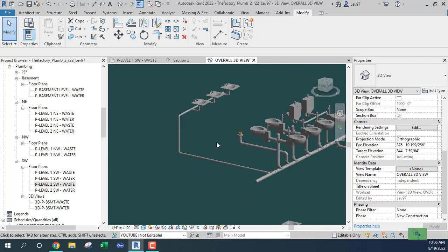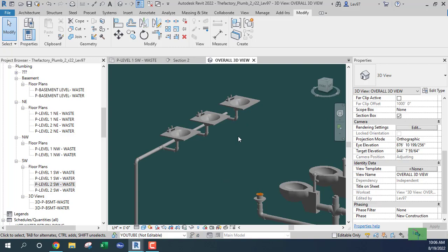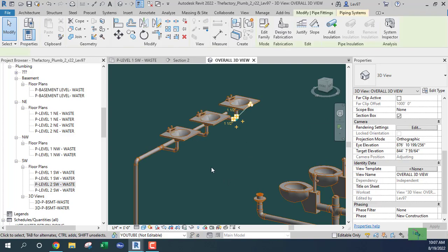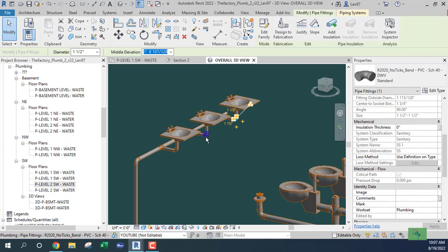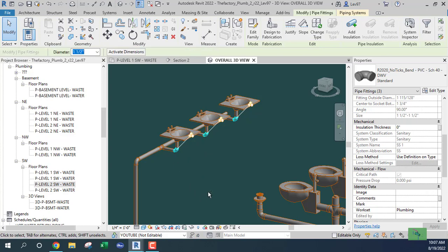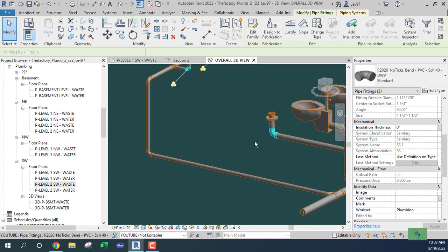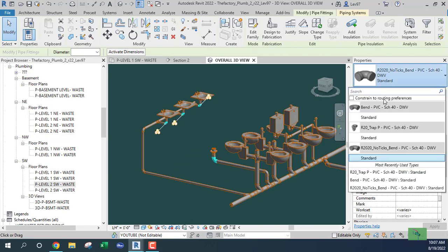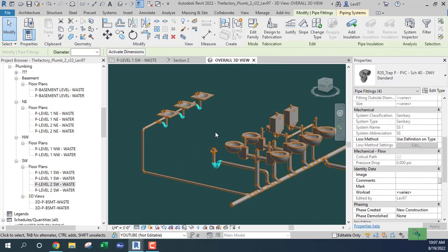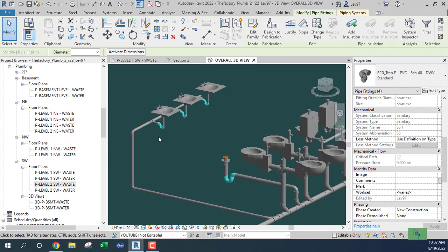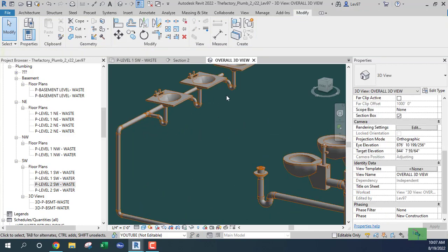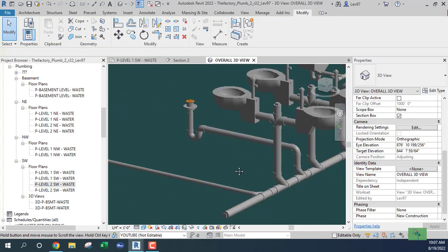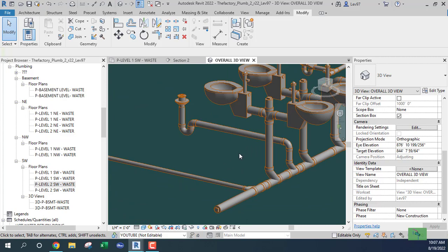And there was more, yeah, P-traps here. So I'm going to click here and do control, control, control, and another control. So I've got 3 elbows that I need to convert into a P-trap, and that's going to be like that. So all of them changed, which is not a big deal. So I have all my traps here.